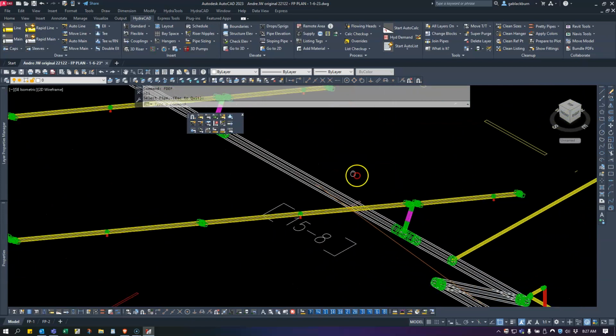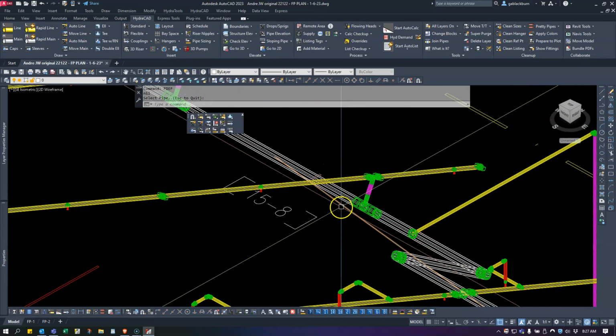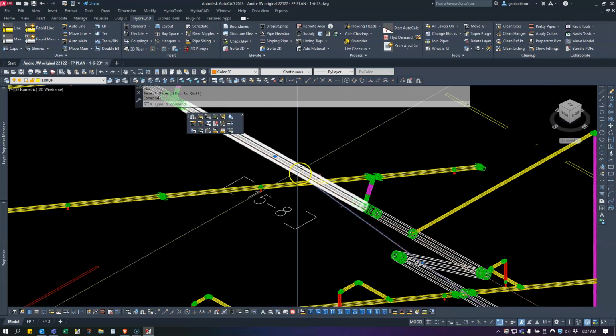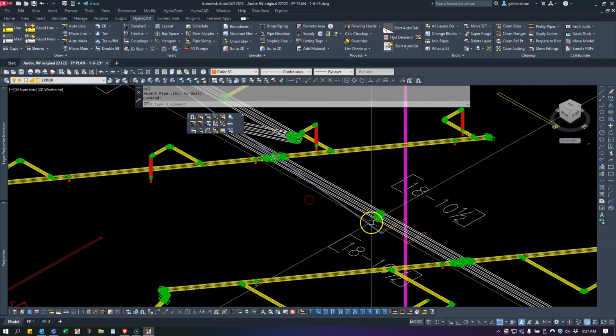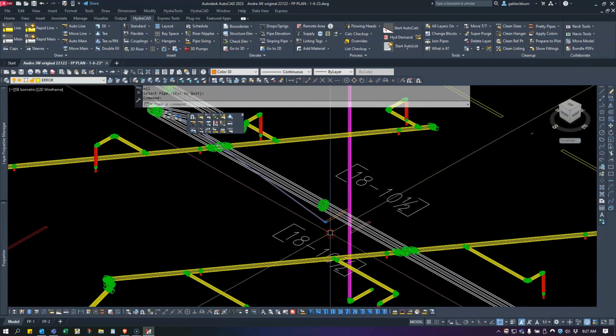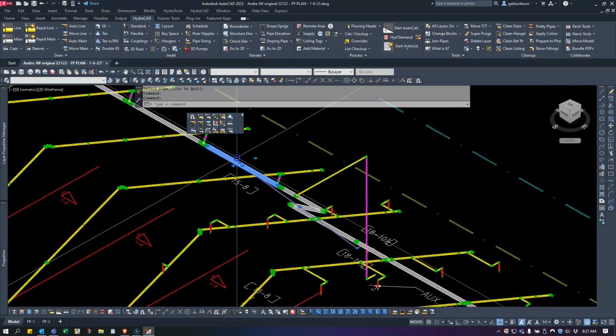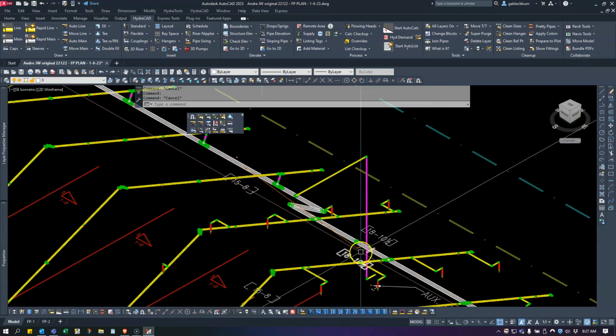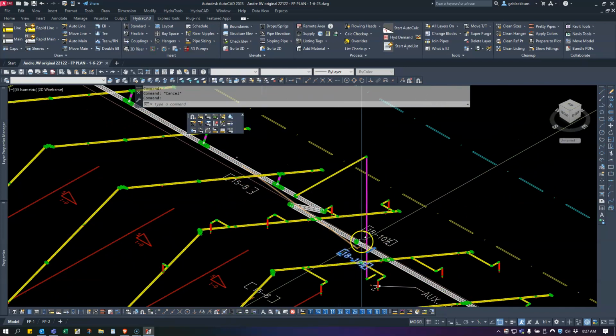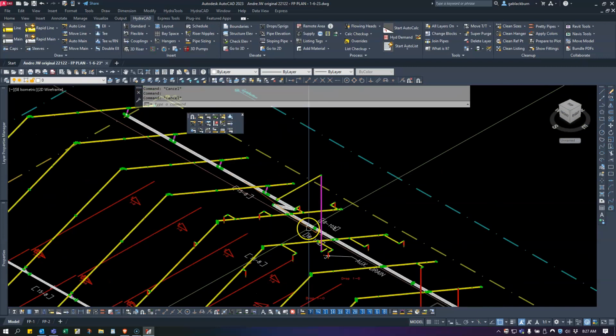And you'll notice it doesn't use that def line. It gives me this construction line, or this interference line, and it's drawing it all the way over to here. So it's actually telling us that, hey, I didn't elevate this pipe off of the 15-foot AFF that you used. I elevated it off of this. So now we can see that, wait a second, something's up here.